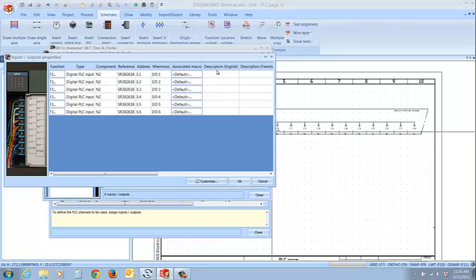In here, I can actually copy out Excel information and insert into my PLC. Typically, the weaknesses of a PLC design lie within the design of its schematic. This should not be a surprise, as it's a meticulous task that's not only time-consuming but also carries the risk of human error. So typos or wrong information can result in undesirable outcomes, which could be costly. By copying out information from your Excel spreadsheet and inserting it into your PLC here, you're going to reduce the possibilities of errors and drastically minimize your design time.